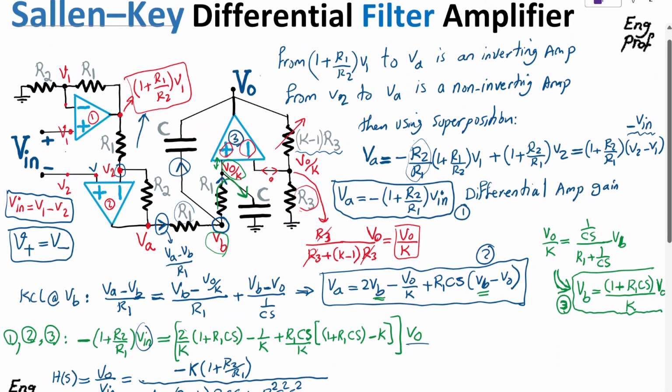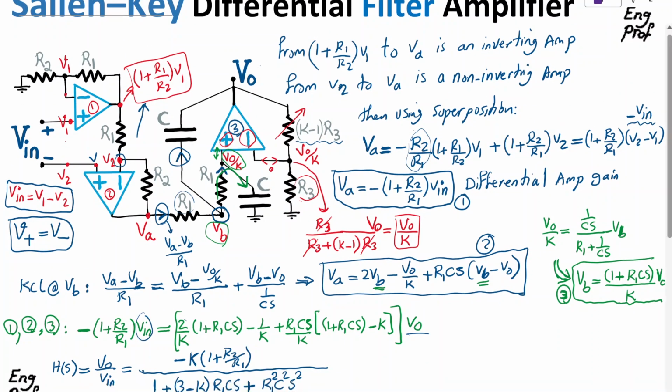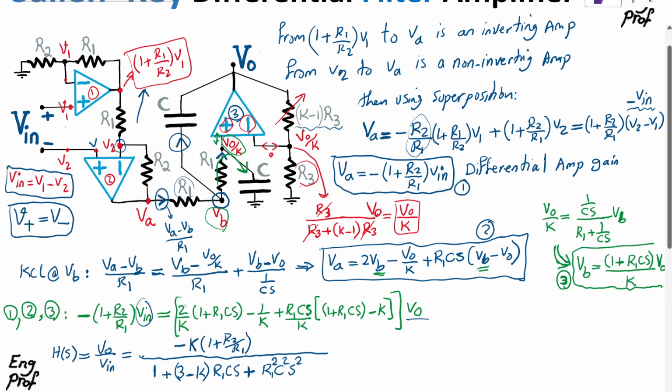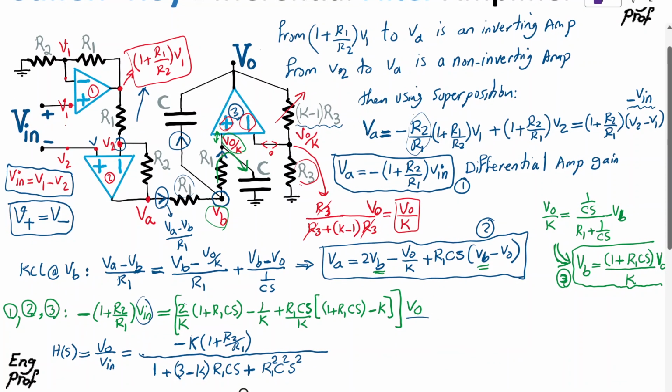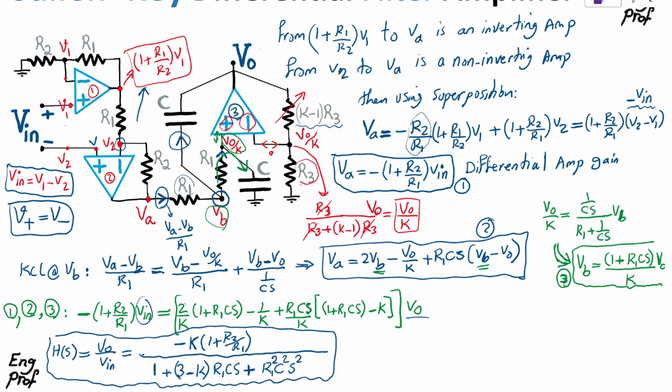So now, what can we say about this circuit? Well, the nice thing is, with this transfer function, we showed the final relationship between the output voltage as a function of the input voltage in a differential fashion, which involved the gain that is controllable using the ratio K and 1 plus R2 over R1, and then in the denominator, we have a second order polynomial in S, which, if interested, we can compute the poles of the denominator, or we can just do it this way.